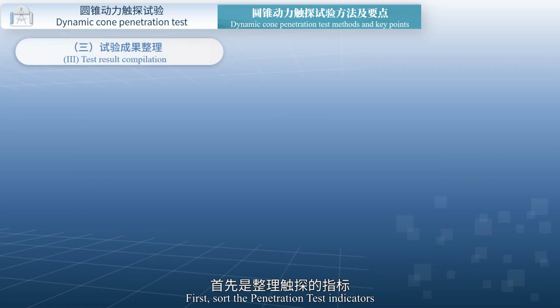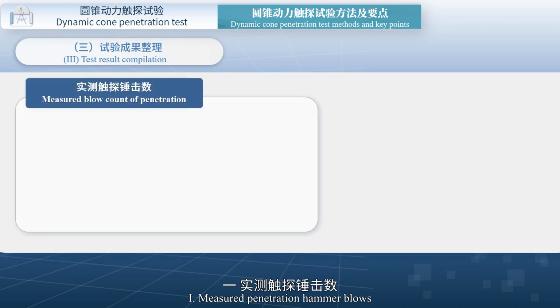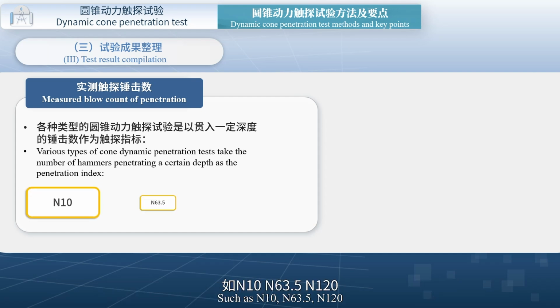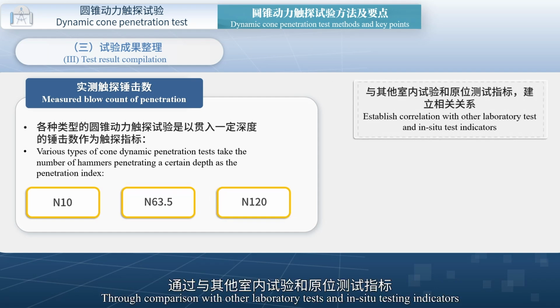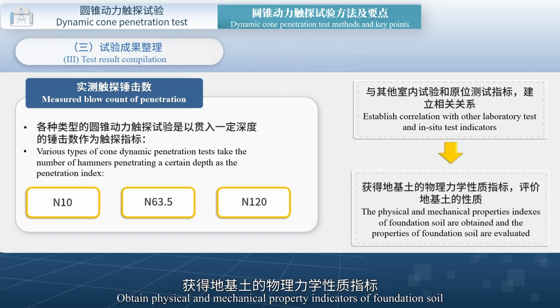Third, test result compilation. First, sort the penetration test indicators. First, measured penetration hammer blows. Various types of dynamic cone penetration tests use the blow count per penetrating a certain depth, such as N10, N63.5, N120, as penetration test index. Through comparison with other laboratory tests and in situ testing indicators, establish correlation relationships and obtain physical and mechanical property indicators of foundation soil.